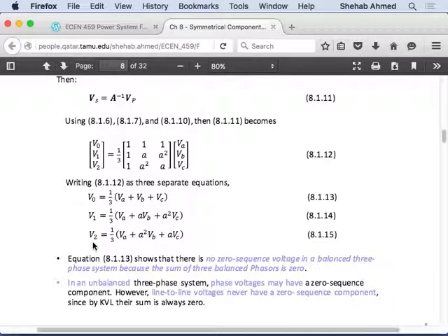Right, because you mentioned that in the case of zero sequence, we always have neutral current, and the only alternative when you don't have neutral current and the system is unbalanced is when you have a line-to-line fault. So what is the condition for having a line-to-line fault? Because it's not a positive sequence, it's not a negative sequence. No, it will have. I'm not saying it will have some positive.